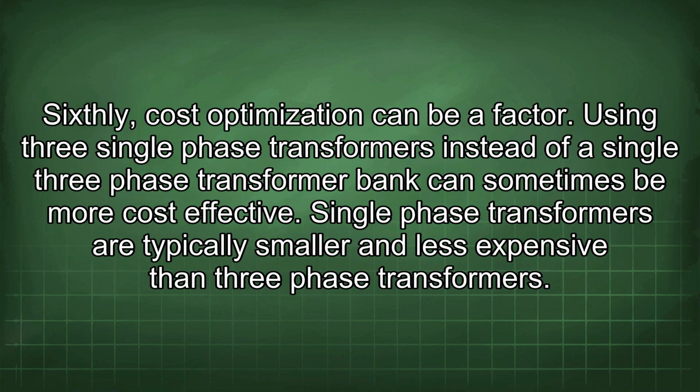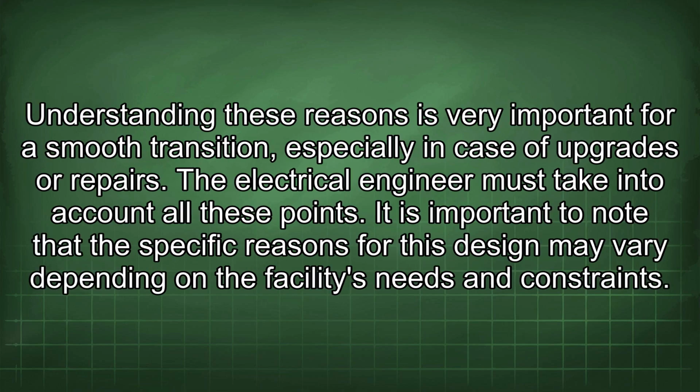Sixthly, cost optimization can be a factor. Using three single-phase transformers instead of a single three-phase transformer bank can sometimes be more cost-effective. Single-phase transformers are typically smaller and less expensive than three-phase transformers. Understanding these reasons is very important for a smooth transition, especially in case of upgrades or repairs. The electrical engineer must take into account all these points.